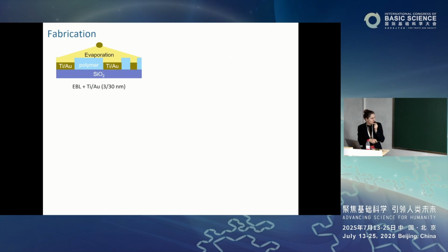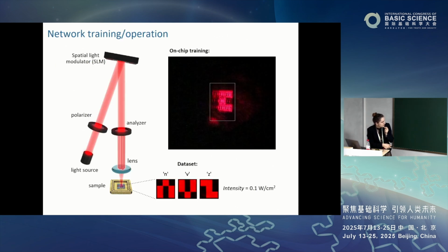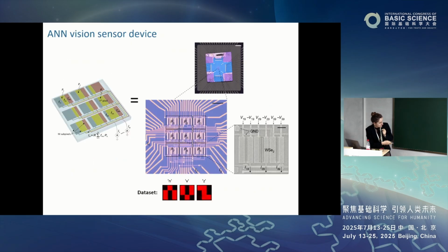So basically, you want to have some insulating and smooth surface, right? Just to start with, it cannot be bumpy. It has to be very smooth because you're talking about nanostructures here. And then you spin coat a plastic onto it, and then you use e-beam lithography, which is basically drawing your patterns with an electron beam on the plastic, and the plastic gets destroyed when the beam touches it. And this is how you can create structures like this one, right?